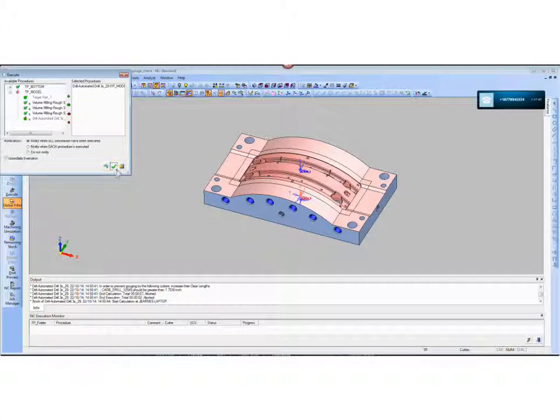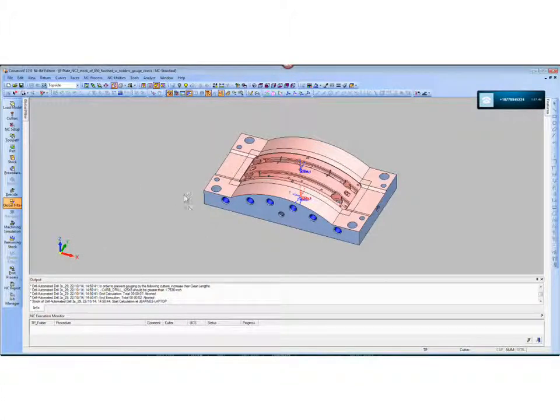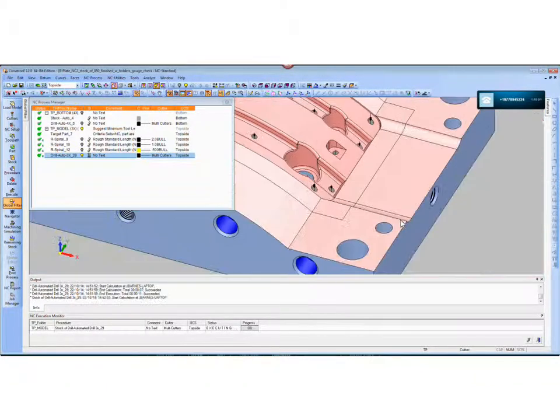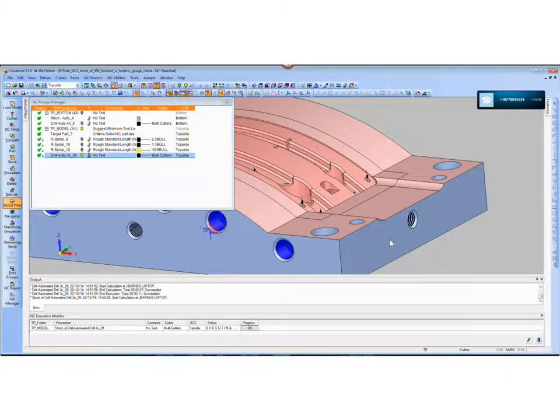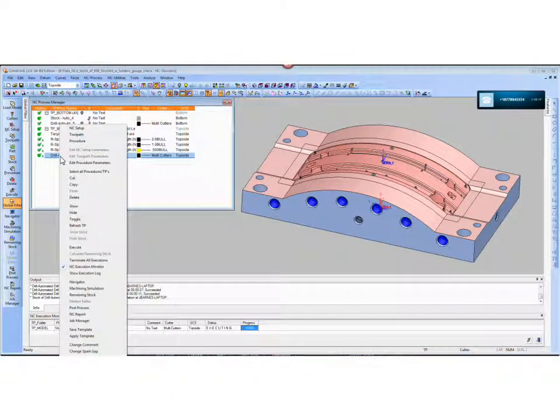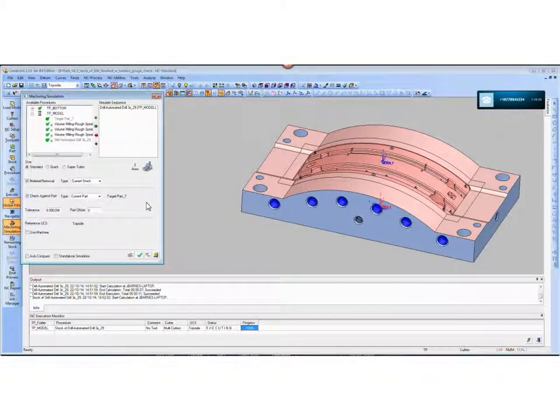And I should get a tool path this time. Although I'm still going to have an issue over here when I go to simulate it. Okay, good. You got a tool path. Again, you can see all the circle millings taking place. And I want to take this one into the machine simulator, and we'll look at what happens when we violate a part condition. Let's see, we're going to use a machine. We'll just use a Haas. We're using the appropriate reference UCS. Let's go ahead and say OK.